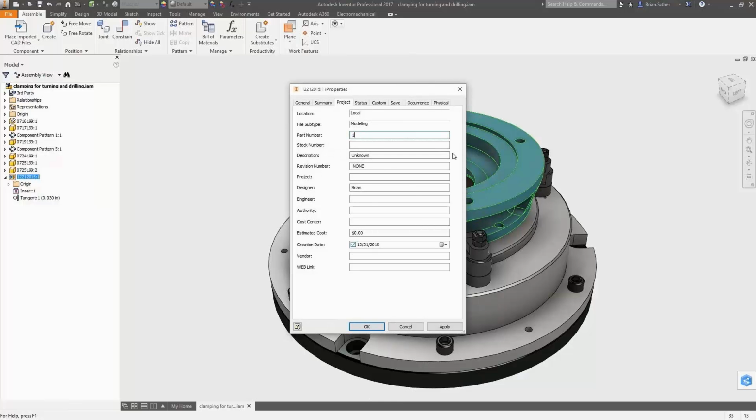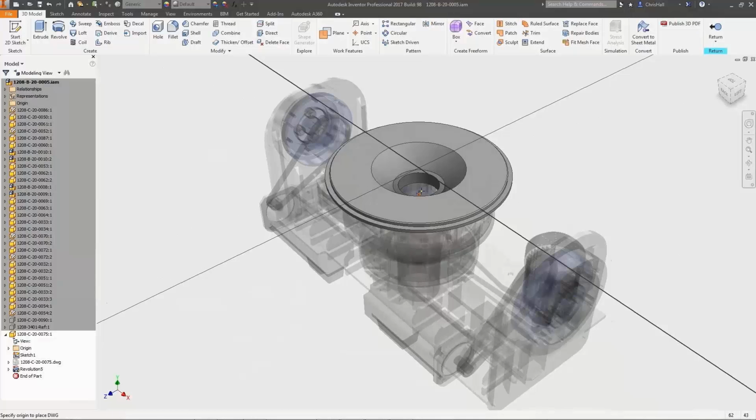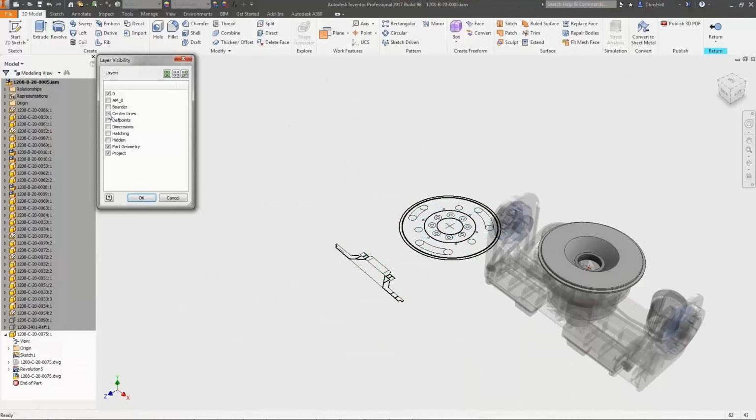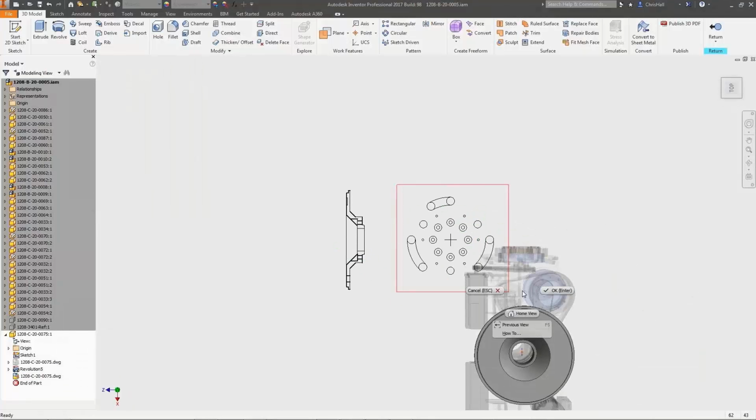Likewise with properties that come from the original file, they will be imported into the geometry, but we can override those, noting that original geometry is shown as black, however the overwritten geometry is shown as blue. In the case where we want to leverage our legacy or AutoCAD files, then we can do that by using the DWG Underlay Technology.